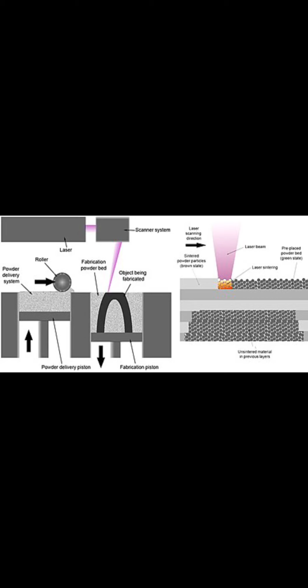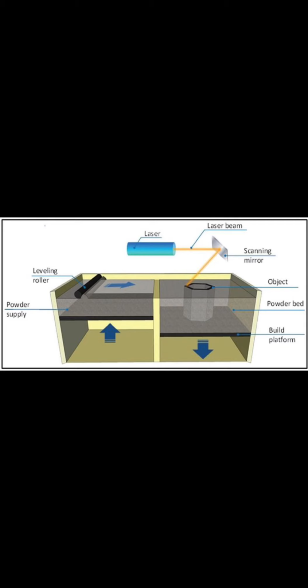The process starts by slicing the 3D CAD file data into layers, usually from 20 to 100 micrometers thick, creating a 2D image of each layer. This file format is the industry standard file used on most layer-based 3D printing or stereolithography technologies. This file is then loaded into a file preparation software package that assigns parameters, values, and physical support.